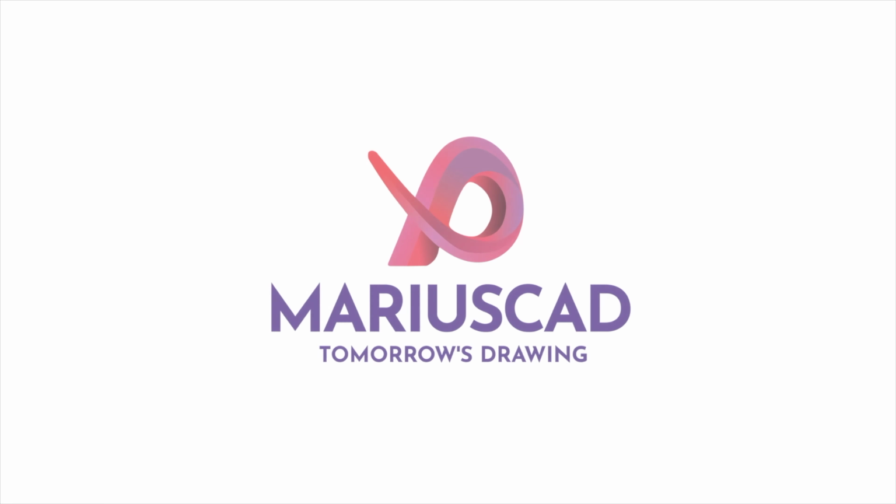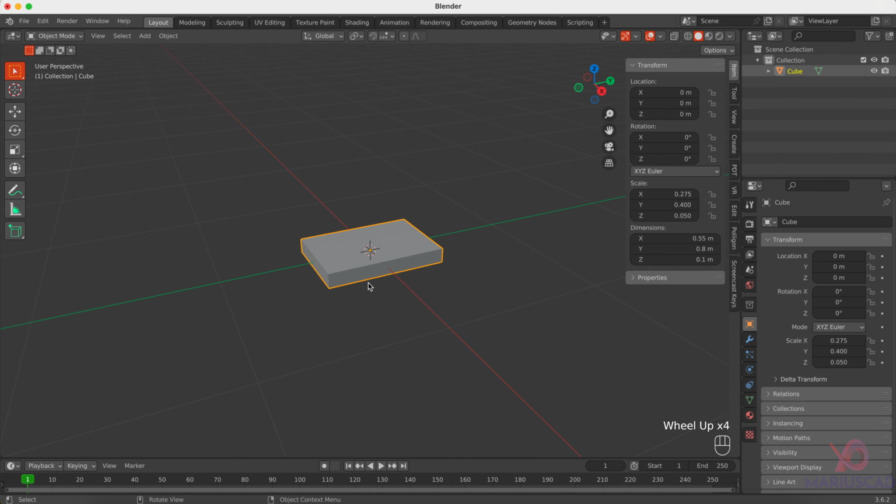First of all, I will delete the light and the camera. I will add them later. After that, I will select the cube, I will press the N letter, and I'll write here the dimensions. I want our object to be on a real scale. So I'll write here 0.55, then 0.8, and 0.1. And our drawing will look like this.